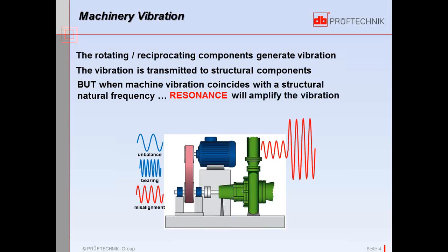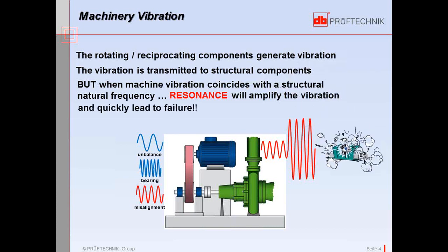So this is one of the factors that we have to be mindful of, particularly nowadays with VFDs, variable frequency drives. It seems that machines operate over a wide range of RPMs, so it's becoming increasingly common for resonance conditions to raise their ugly head, so to speak. And of course that will eventually lead to failure in the machine, either in a catastrophic sense, or a failure of a component, or a failure of the machine to perform the work that it's intended to.